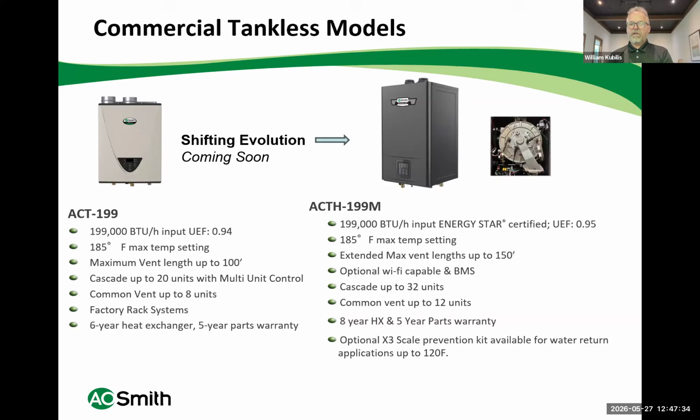There are only two welds just at the connection point where the water enters the combustion chamber and leaves. Both our tankless models do go to 185-degree water, and the one nice thing about tankless is once you set it to 185, it's pretty accurate as far as the delivery temperature. It will deliver 185, maybe 184, but they are very accurate, and especially for areas where sanitizing rinse water is required. Making sure you have 185-degree water all the time, or 180-degree water at minimum,